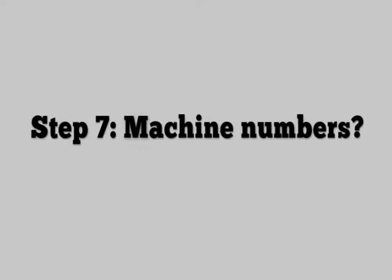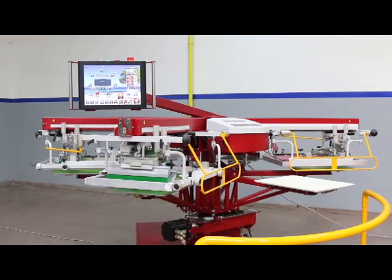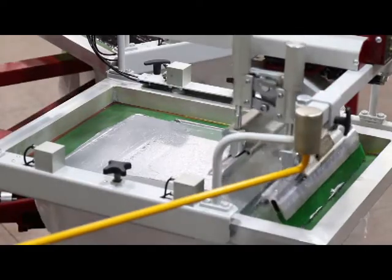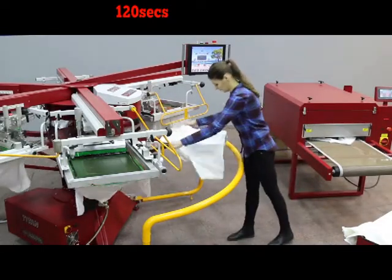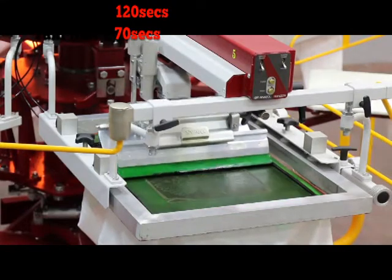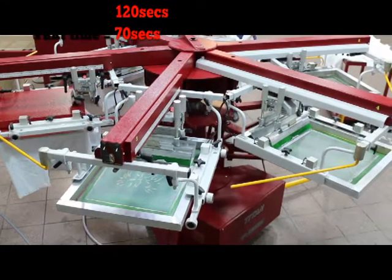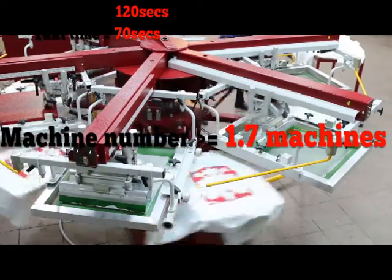Step 7. Determine how many machines are needed. Once you know the takt time and the time standard for each operation, divide the time standard by the takt time. That will give you the number of machines. For example, you have a printing machine with a time standard of 120 seconds per printing. The customer demands a takt time of 70 seconds per printing. How many printers are needed? 120 divided by 70 equals 1.7. You will need to purchase 2 printing machines to meet the demand.